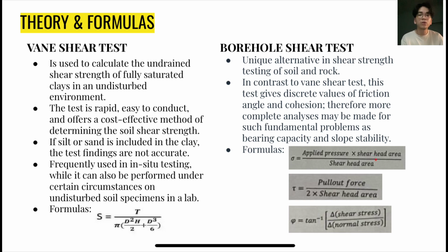So the borehole shear test is a unique alternative in shear strength testing of soil and rock. In contrast to the Vane shear test, this test gives discrete values of friction angle and cohesion. Therefore, a more complete analysis may be made for such fundamental problems as bearing capacity and slope stability. The formula is given as below.